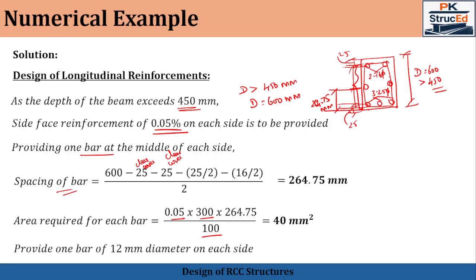For this we are providing one bar of 12 mm diameter, which is more than 40 mm square. So we are providing one bar here, 12 dia, and here also 12 dia. Those two are the side face reinforcements.